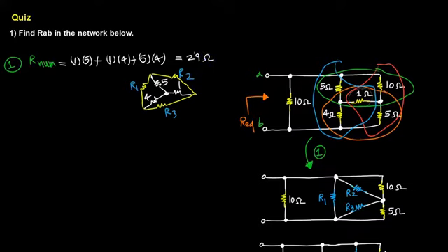The next step is, for any given resistor that we're interested in, we would do this. Let's find R1. R1 is opposite to the 1 ohm resistor inside the Y network. Do remember that we're going to reference the opposite resistor in the original network that we want to convert from, the Y network, not the delta network.